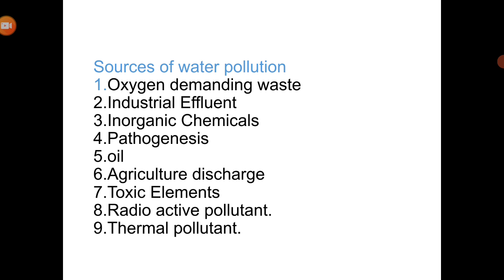And agricultural discharge. We know that in order to improve our agricultural production, we are using a lot of fertilizers and pesticides in our agricultural land area. The water soluble compounds containing nitrate, phosphate and ammonium ions induce the excessive growth of plants. Due to flood and cyclone, these nutrients are leached by surface runoff and reach the nearby aquatic water body.